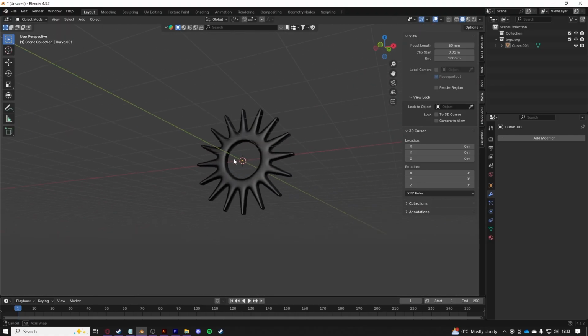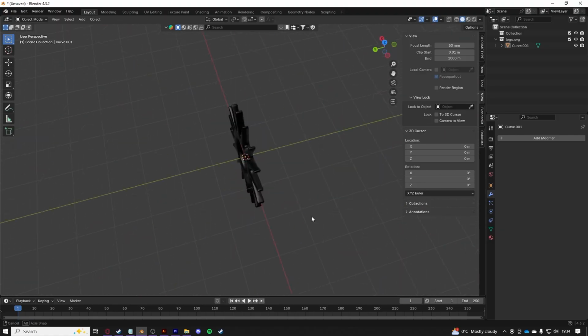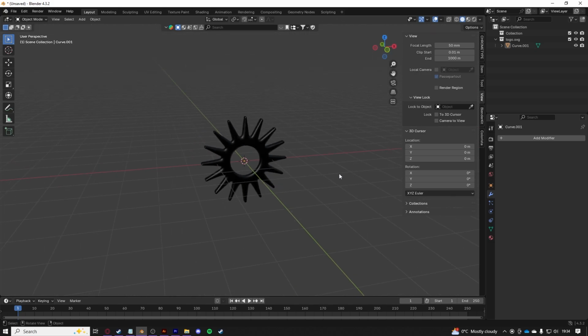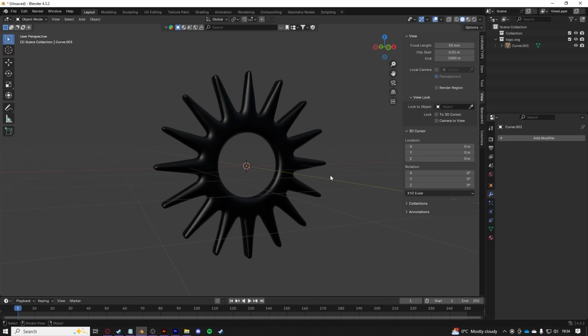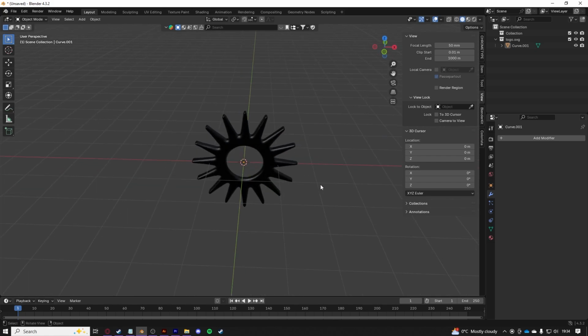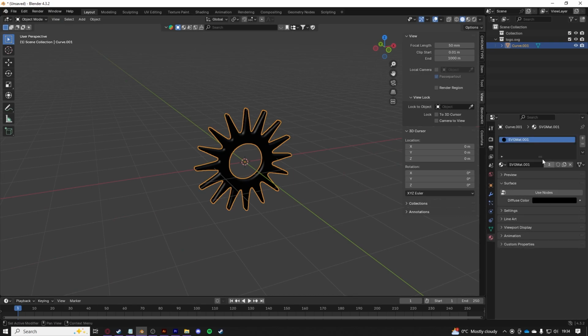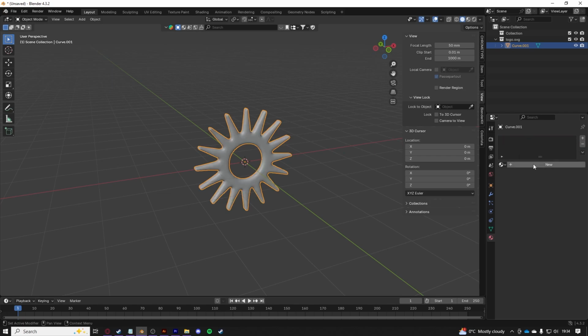Okay, so we've created our 3D object. Looking good. So first of all, you can go down 2 routes for making this chrome. As a graphic designer, I'm not the best texturer in the world, but I have my workarounds. So if I select this, I'm going to go to material down here, and there's already one here, SVG matte. It's applied to all SVG files for some reason. I'm going to press this minus button to get rid of it. We're going to create a new one,